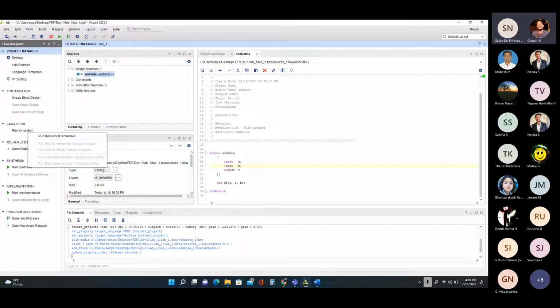Why? Because logical errors you cannot see in the terminal; it will only highlight syntax errors. In the hardware description you might have written the syntax properly, but the tool is not able to understand what is in your mind, and it is not able to transform the RTL description into a gate level netlist, so it will do some trimming somewhere else.